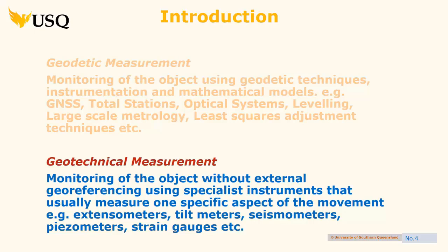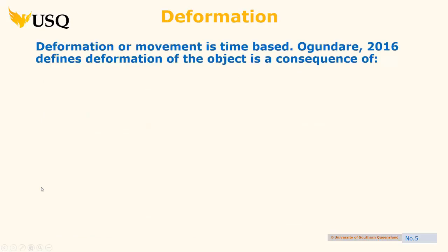Geotechnical is the monitoring without someone measuring externally, right? So they're specialist instruments. Some of them are actually buried inside walls, quite commonly in dams and bridges and other structures. They are physically inside the walls, right? Wivenhoe Dam has quite a number of them that just continually monitor by wire. The new techniques are now moving more towards wireless, Bluetooth, things like that. And we'll cover those in reasonable time, briefly.